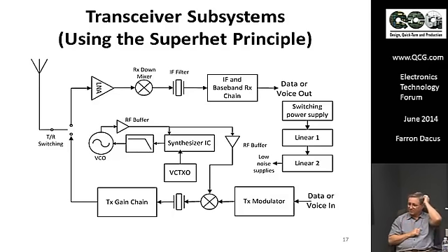I thought there was direct conversion inside the chip. There's no coming out of the chip to a filter and going back in. Yeah, but the problem with even direct conversion, where you can get very low bandwidth at baseband, is that you've got phase noise on the oscillator that does the converting.